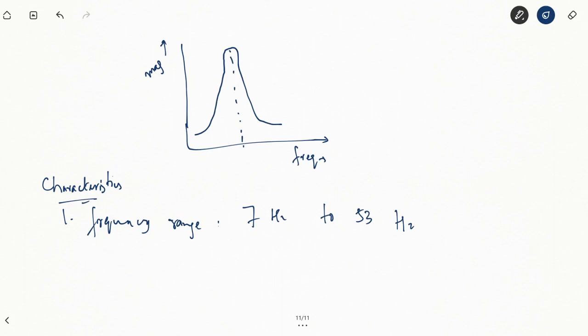So what are the advantages of this mechanical resonance device? The indication will be independent of the supply voltage. That means the vibration of the reeds is independent of the magnitude of the applied voltage. It only depends upon the frequency of the applied voltage.